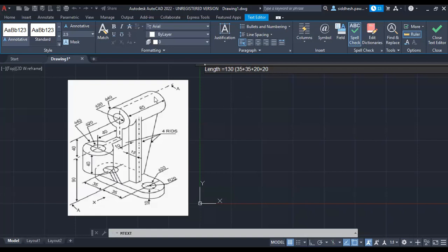Yes, sir. Let me explain again. See this distance 65, then 45, then next 20, which is a diameter 40, so the radius is 20. Then it drops down, the full 40 goes inside, then it slopes down and comes here, and then it ends. So that is your 35 plus 35 plus this 20. And a similar semicircle is made on the other side as well.